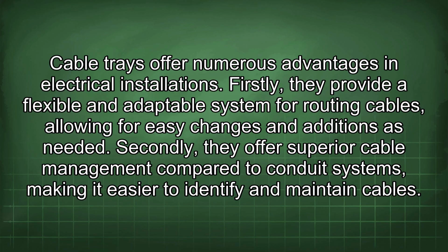Cable trays offer numerous advantages in electrical installations. Firstly, they provide a flexible and adaptable system for routing cables, allowing for easy changes and additions as needed. Secondly, they offer superior cable management compared to conduit systems, making it easier to identify and maintain cables.